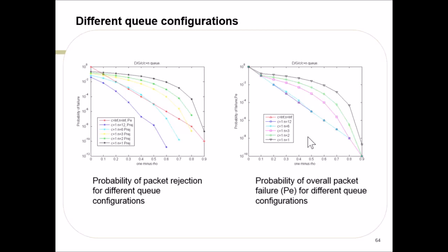Yeah, usually one concept we use is, say for instance, the hard disk drive, you have a sector of 512 bytes initially. Now we use 4 kilobyte sectors, and what is the LDPC code word size? That's up to you in terms of the design. We used, for instance, less than 512 bytes initially for LDPC for lower complexity, and then we moved to 512 bytes. For 4 kilobytes you can have a 512 byte code word itself, but you can interleave those 8 code words together to form a bigger code word. So the LDPC code word is independent of the sector size or the page size, but usually the preference would be that it's closer to the page size or sector size you want to write.